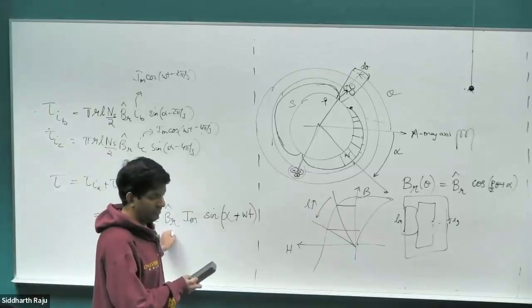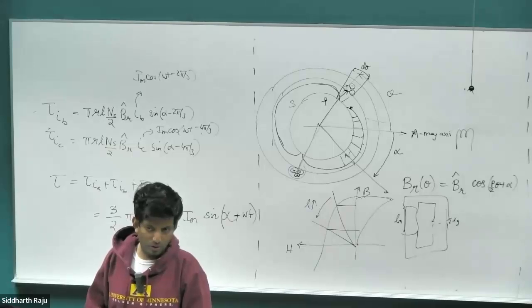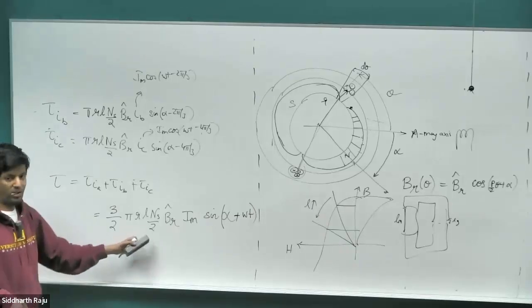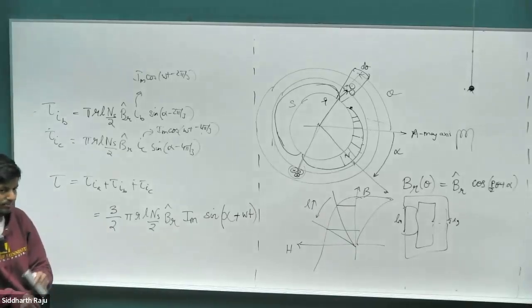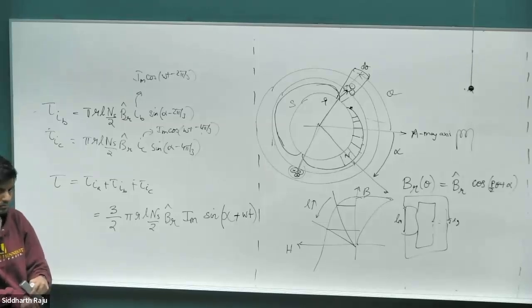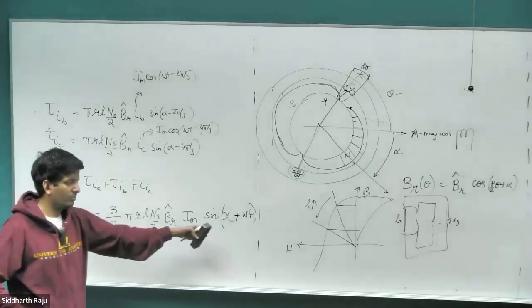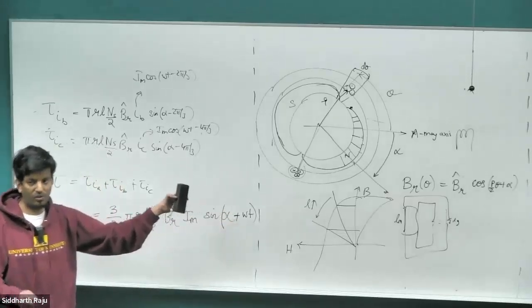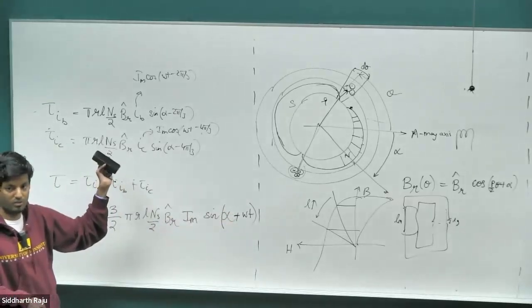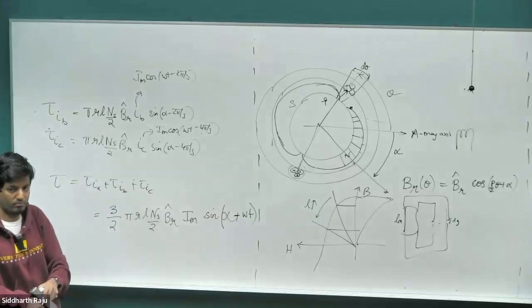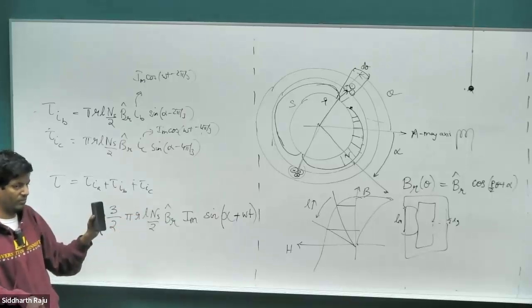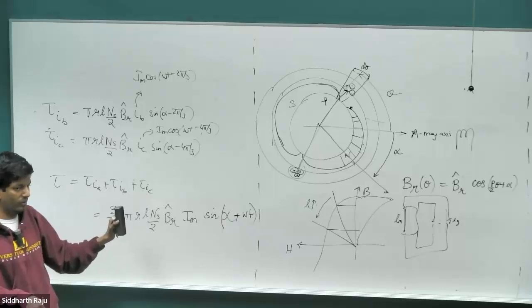Will the motor experience a torque? No. Will the rotor be experiencing a torque? So the expression is this one. Let's say the rotor is standing still, and this is varying sinusoidally, right? Because omega t is varying sinusoidally. What will be the net torque? Same problem as what we have on the right there. My torque is going to vary sinusoidally if my rotor is at standstill. So the net torque created by this motor will be 0.